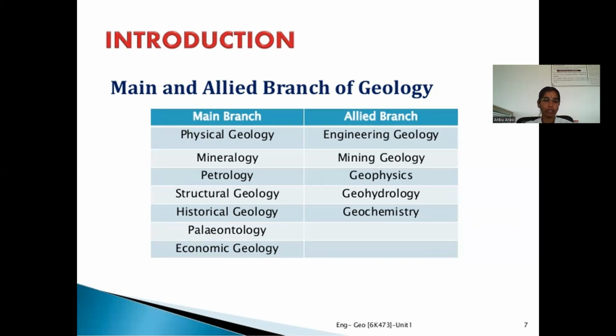main topographic features and natural drainage pattern, then structural characteristics of rock formations such as their strike and dip, folding, faulting, and igneous intrusion, rate of weathering and erosion in the site, lithology and engineering properties of rock, and groundwater conditions. For obtaining these details, conventional geological and geophysical surveys have to be conducted.